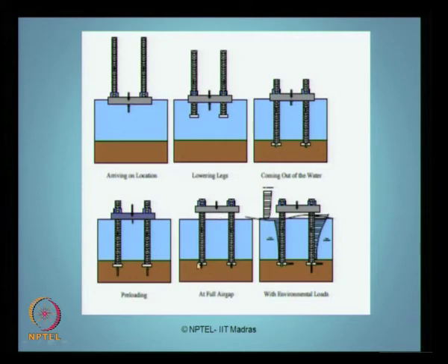Once it is installed with an air gap, now the jack-up rig is ready for encountering different environmental loads caused by waves, by current, and by wind as well. So this is a schematic view of how a jack-up rig is actually towed to the site, installed, commissioned, and then made ready for exploratory drilling operations.